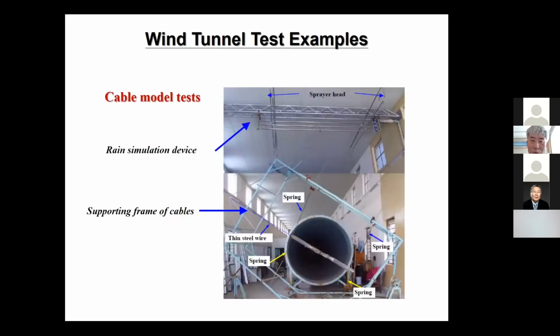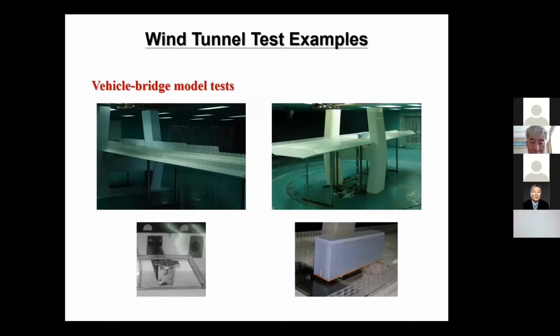Another issue we do wind tunnel tests on is rain-induced vibration of cables, a wind vibration test of cables. We have a rain simulation device. It has a spray to simulate the wind and rain, and we have a spring and a cable here, trying to simulate the rain-induced vibration. Also, we have a vehicle bridge model test.